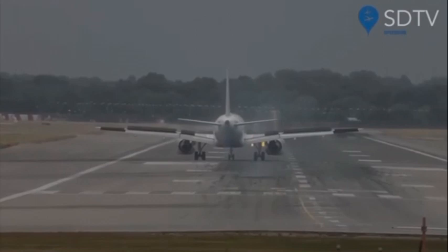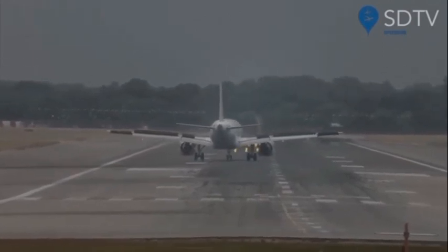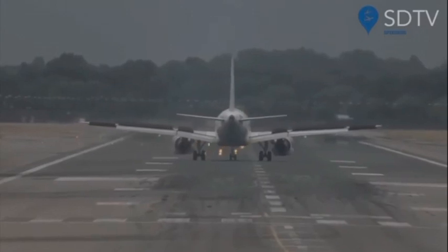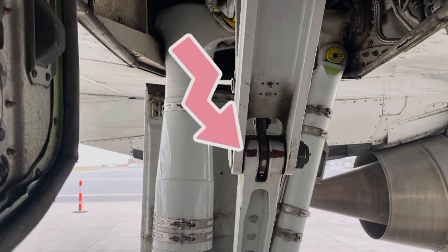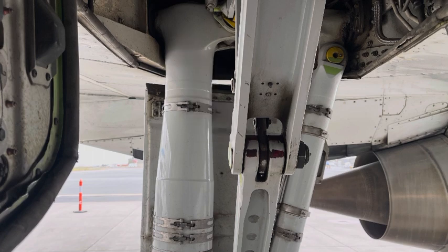For all landing gears, mainly the main left, main right, and nose, we have some markings and drawings which ensure that the landing gears are fully down and locked. So if, during the flight, we get a problem with the landing gear and we are manually extending them, and we do not get the proper lights above the landing gear lever, we have some viewing ports which the pilots or mechanics on board can look through, to make sure those red lines are aligned.